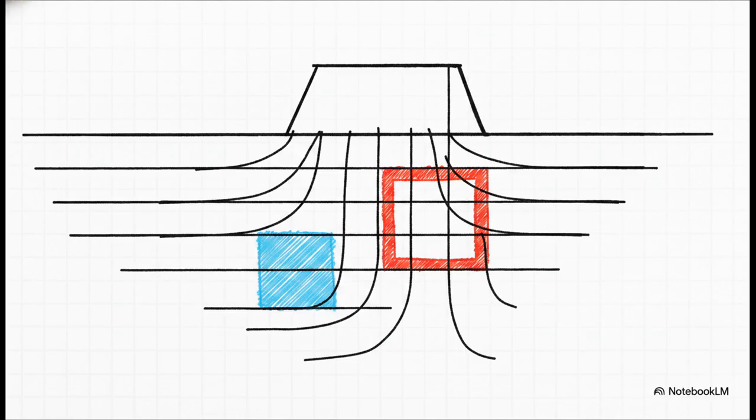So why do we even bother drawing these intricate nets? Well, their engineering applications are honestly real game changers. We use them to calculate total seepage discharge, figure out the pressure distribution, pinpoint the hydraulic gradient at any given spot, and calculate that terrifying uplift pressure we talked about earlier. You literally can't design a safe dam or sheet pile without them. Oh, and a fun fact for you, when those lines cross at 90 degrees, they form these neat approximate little shapes we call curvilinear squares.